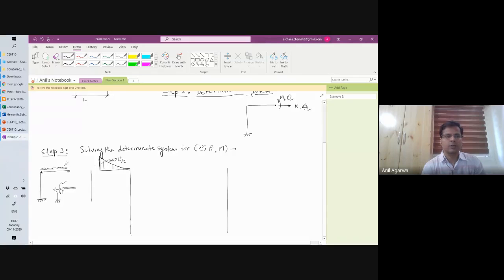So again, you can imagine that this is a cantilever. Plus, in addition to that, there will be a vertical downward force. But the vertical downward force will be purely an axial force, and it will not contribute towards the moment. So you can ignore that for bending moment diagram calculation. Okay. So it is there, but I'm not considering that for bending moment diagram calculation. So basically, you again got another cantilever. In that cantilever, you have a moment acting at the free end.